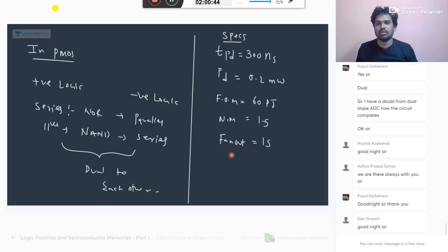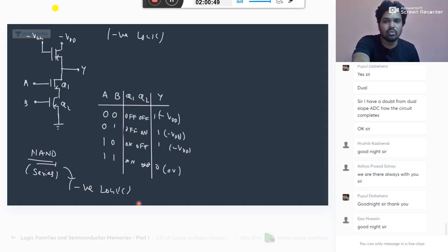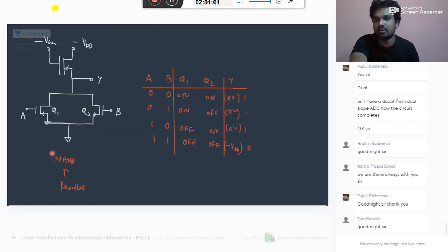Right. So anything else? One more thing I want to specify: see, NAND gate is directly coming. Inversion comes for free. NAND gate is not made by AND followed by an inverter. NAND is directly available. NOR is directly available. So you understand, inversion comes free compared to direct. In fact, an AND gate can be made by adding one inverter here.